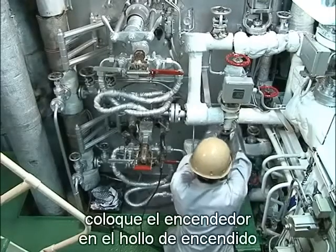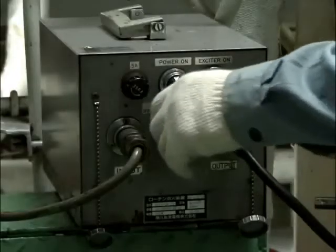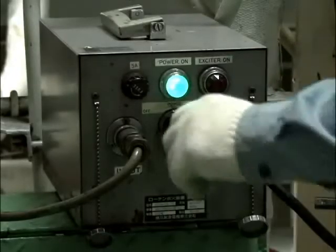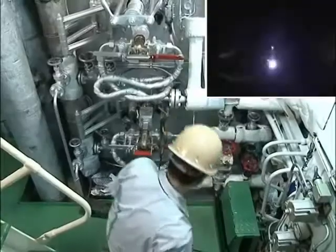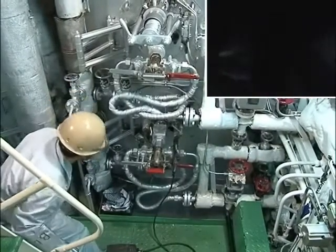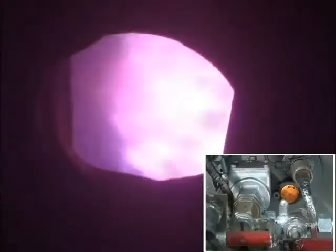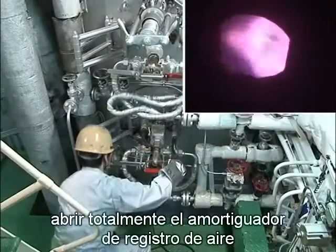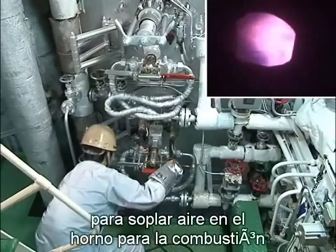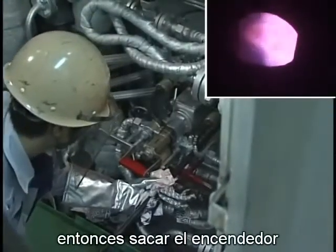Insert igniter into ignition hole. Turn ignition switch on and depress foot switch. This opens the air-driven fuel oil piston valve and atomizes fuel oil. After ignition has been confirmed, fully open the air register damper to blow air into the furnace for combustion while observing the state of the flame. Then pull out the igniter.